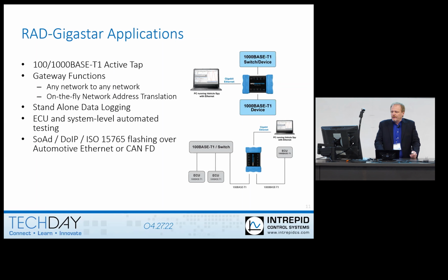It supports Ethernet, so you have the different protocols: SOME/IP, diagnostics over IP, flashing, Automotive Ethernet or CAN FD. The embedded function blocks, that's what I was alluding to with the standalone scripting and the embedded processor. Function blocks are GUI driven, basically a state machine generator.